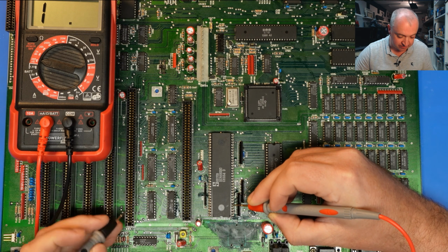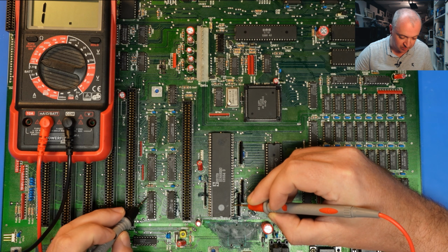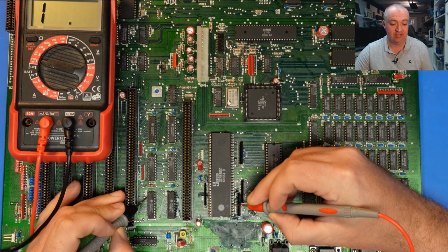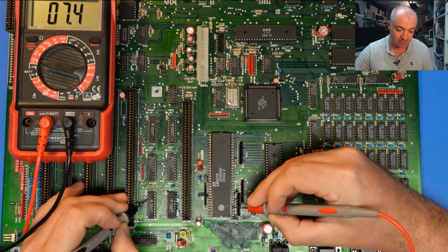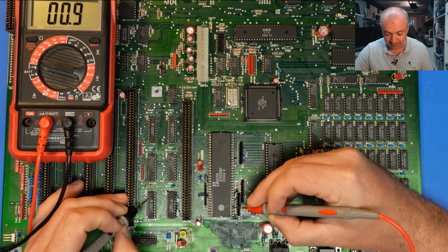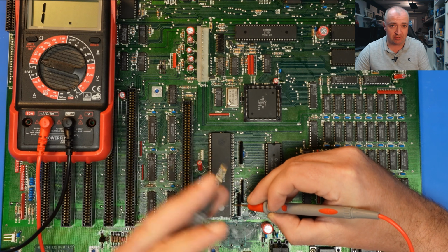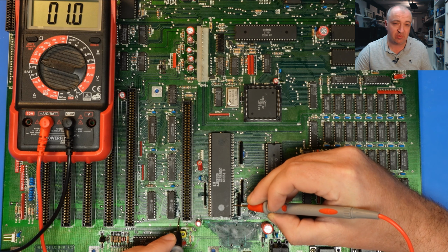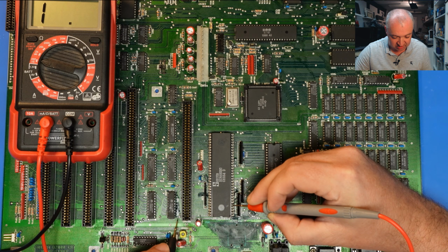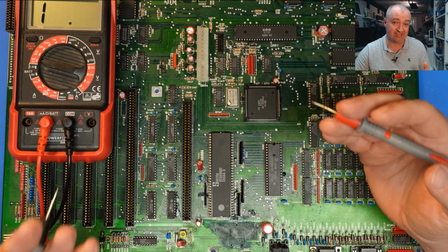If we go on to that, D0 should be connected through to pin 2 of U603, and it's not. Data line D1 should be on pin 3. Well, that's okay. But D0 is yet again broken. Now we can't trace it through the board to a via at this point. It makes its way to there, but there's a crack in the trace just as it joins onto said via. So that's definitely the problem related to the Zorro slots, or at least I hope it is.